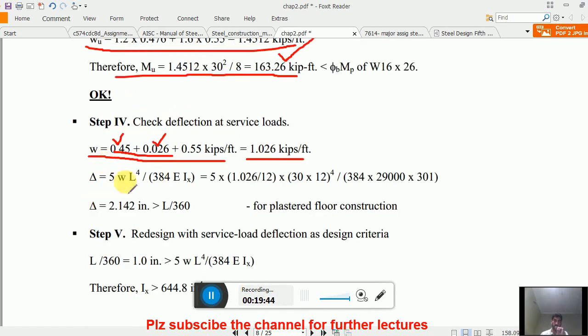They just find out the deflection, and the deflection is 2.142 inches, which is greater than L by 360. So it doesn't pass the limits, because it is beyond the limits, it is outside the limits. So that's why we have to redesign the section.